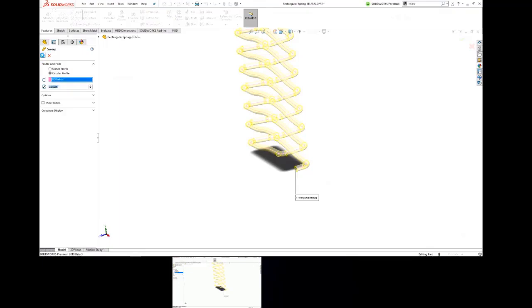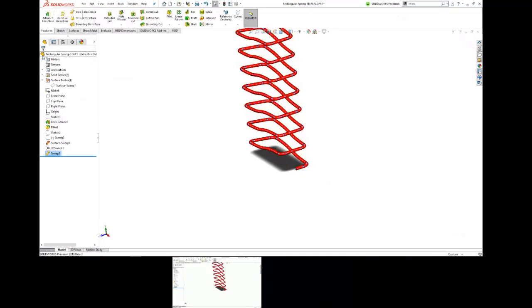Hey, Brad, quick question. If I only wanted to do a few segments of that curve, how would I change the pick? In this case, it's grabbing the entire sketch. So since you're in 3D sketch mode, just go convert those to construction geometry or delete them or modify them, whatever.